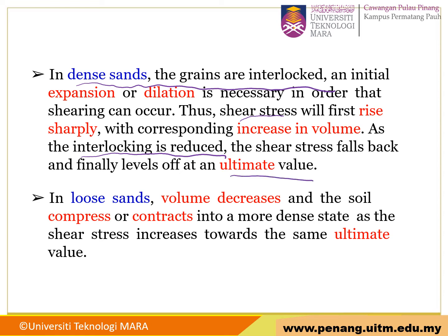Alright, this one is for dense sand and loose sand. For loose sand, volume decreases and the soil compresses or contracts into a more dense state as the shear stress increases toward the same ultimate value.